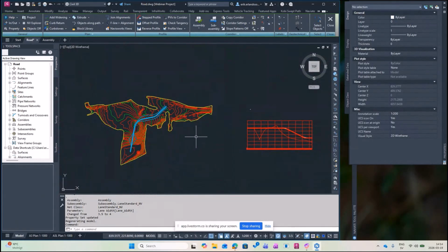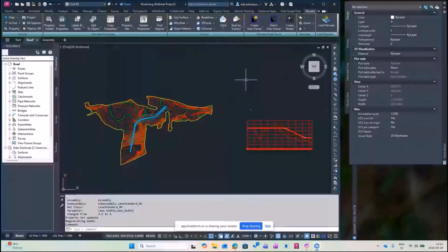The second thing I want to do is some surface management, file management, and corridor management. Let's start with our surface. We have a tool that's called Style by Surface. That tool lets you update all styles associated with a selected surface in one place. Instead of adjusting styles property by property, you manage them through a single property set. So let's go ahead and click Style by Surface.